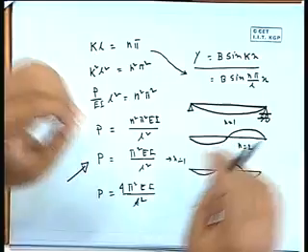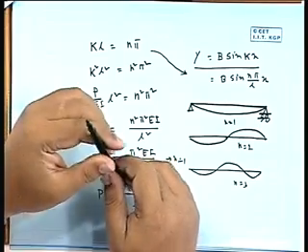Now in a normal case, if it is a perfect case, it will try to deflect or fail in the fundamental mode or first mode, because it will require less force. Now if you try to prevent it here in the fundamental mode, the middle part will undergo large deformation. Say there is a column, and centrally there is some resistance. Due to the load it will try to buckle, and centrally some member is passing, so it is preventing it.